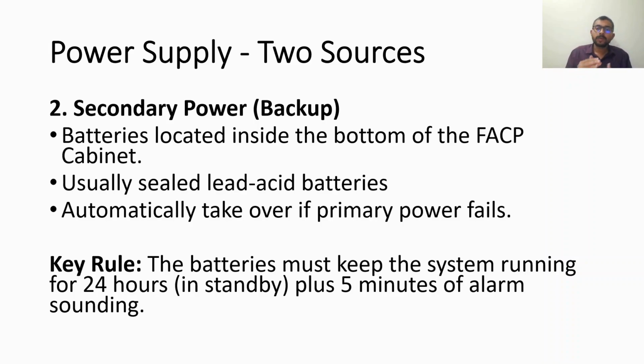Because whenever you do testing and commissioning, the consultants or the inspectors will check the battery test. When you perform the battery test, they will ask you to disconnect the main power supply and run the panel in standby mode. So it's like you're running the panel only on batteries.